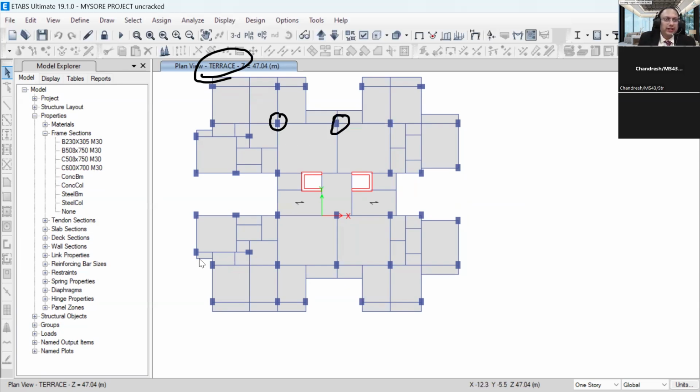See, I think you are working on the uncracked model. You will go to the service crack, strength crack, and all actually slowly, and then you take a call on this. Currently, I'm sure that you are working on the model analysis and other things, but since you have gone for the buckling analysis, which is the ETABS advanced part, over the period of time you'll see how you can give the economized location or the sizes of the columns.